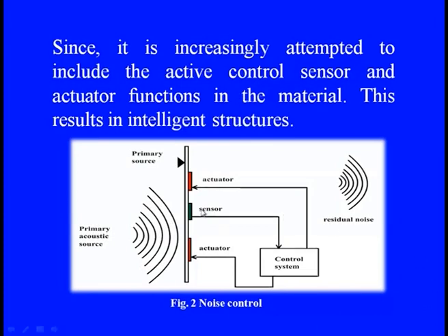and this sensor, as we discussed already, immediately senses how much the acoustic level or the exciting feature of the vibration is in terms of displacement, velocity or acceleration. Accordingly, we can adopt the sensor. One of the basic features of the sensor is that whatever property is to be sensed, we can straightway physically put that part. Like if we want to sense the displacement, which is one of the basic dynamic parameters, the displacement probes, LVDT, strain gauges,